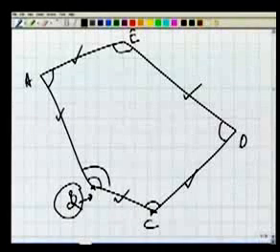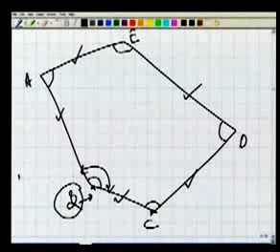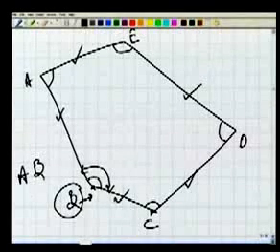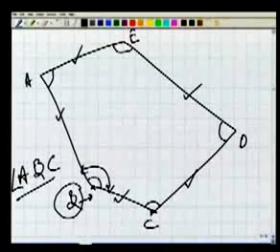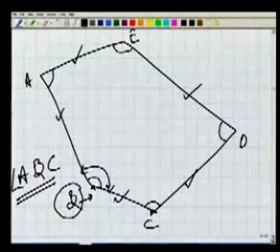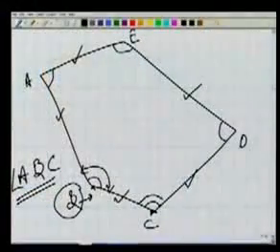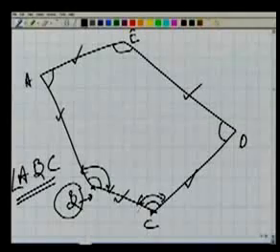Let's say our theodolite is at point B over here, and we want to measure the angle A, B and C. This angle is required. So what all should we do? Once we have measured the angle at B, we will move our instrument to C in order to measure the angle BCD.